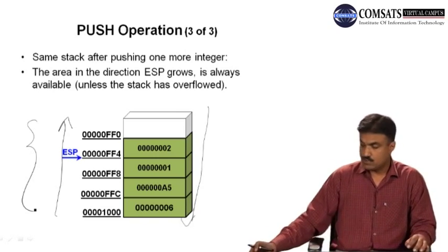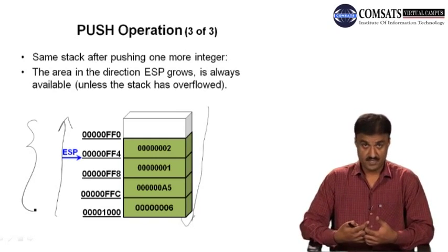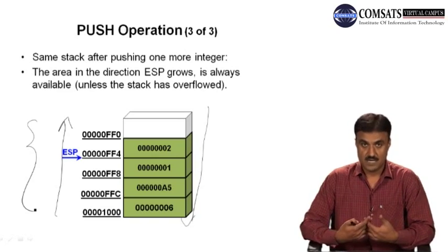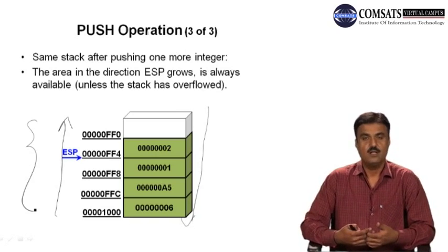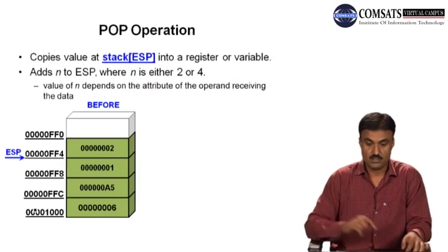So this was the push operation. Just remember one thing: before pushing any value, the stack pointer is decremented by the size of the operand, or value, that we push inside the stack. Then the element is added at that location.